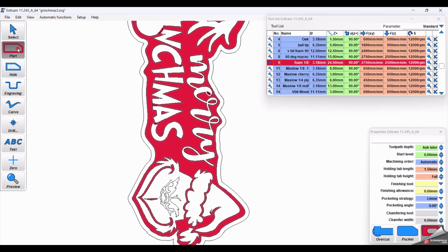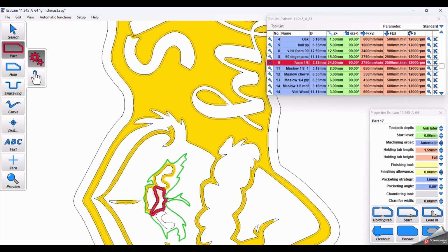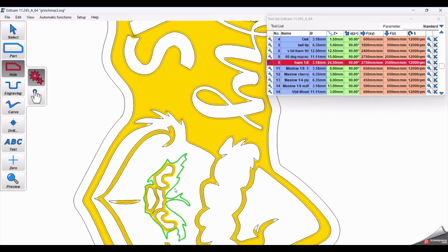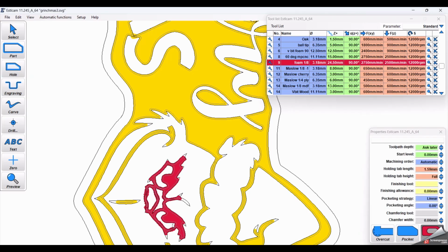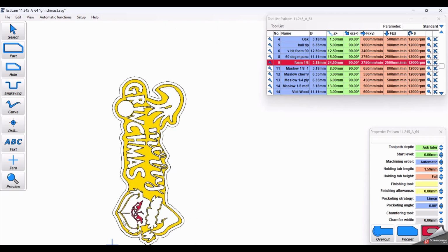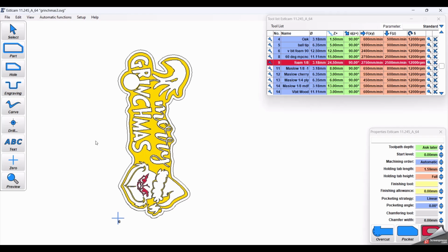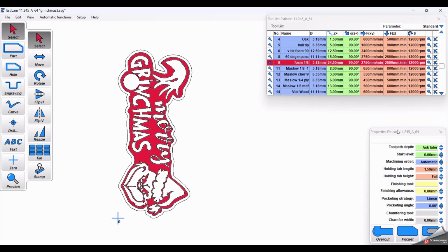So it will find some pattern. You can do the same thing with his face. You do parts around the inside pieces, do a hole around the outside piece, and then select island, and it fills that part in and will remove that as a pocket. But it's a functional pocket with pieces that don't get cut. So there are patterns inside the pocket, and we call that an island. Then we select everything, and we set the pocket depth at 5 millimeters.